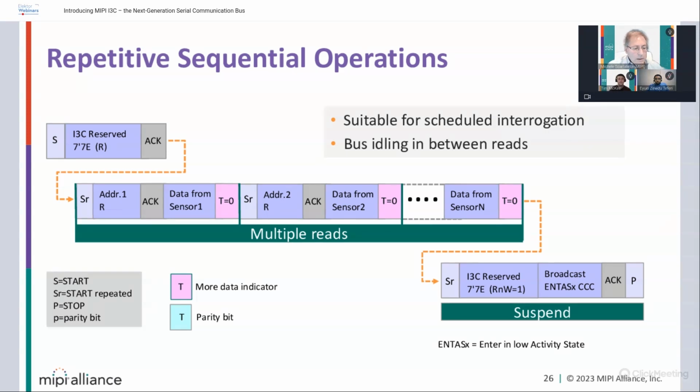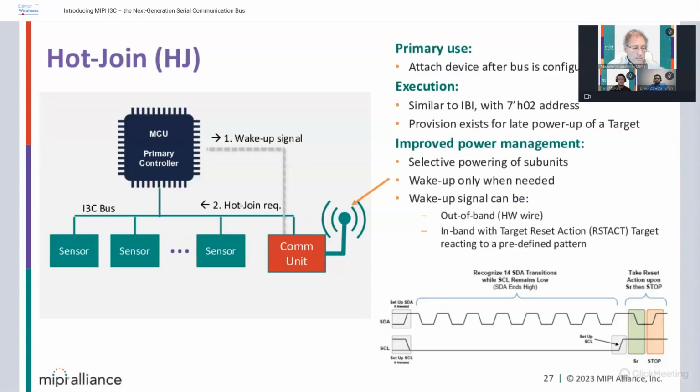Here, by combining a scan, where you use the repeated start and read a bunch of sensors, and then use a command mode, enter bus status low speed, you wake up, acquire the data, maybe with the asynchronous mode also with very precise timing information, and go to sleep. For repetitive data acquisition, it's very efficient in power and also in computing.